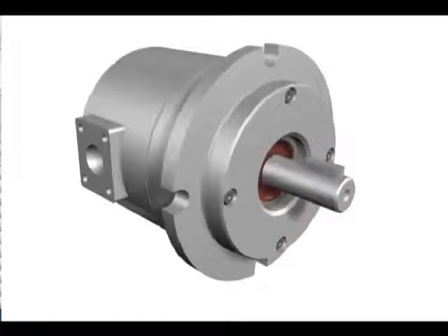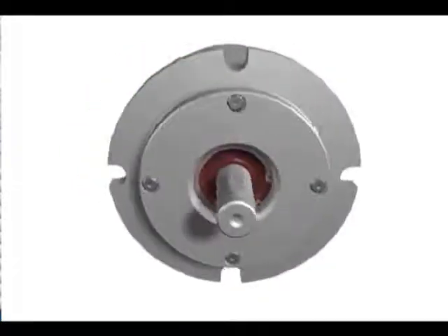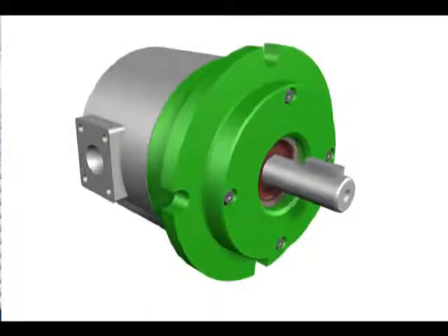Of the three designs, the main components of the crescent pump include the housing with a crescent seal and ports, the end cover, the input shaft, the drive gear, which is an external gear, and the ring gear, which is an internal gear.